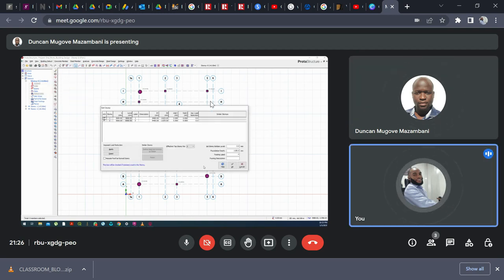So if you want to add your height now, your height of building, you see that place called H, that tab after story called H. You can add your values there for your height. But since I've already run this analysis, there's no need, because if you do it, it will cancel all what you have done before. So I would have to reanalyze now. But just leave it. I just want to show you, so that the next one that you'll be doing, if you have different heights, you can come here and change your height.